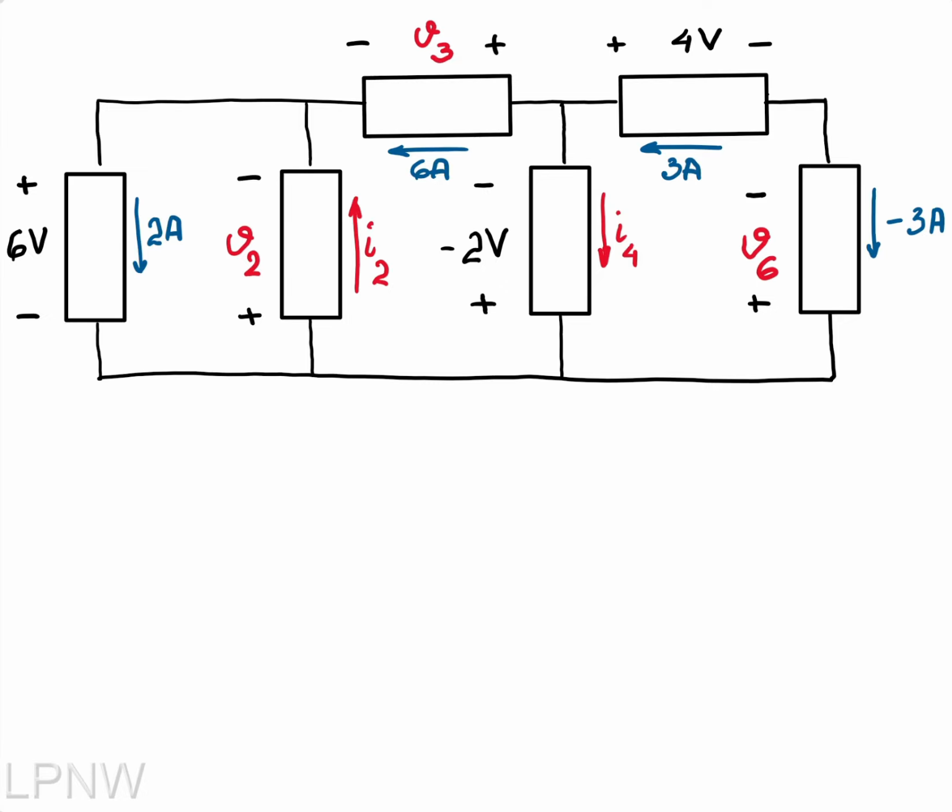It indicates that the algebraic sum of all the voltages inside the loop equals 0, and one very important point in here: never ever change the direction of the loop. Once you choose one particular direction for one of the loops, exactly the same direction has to be applied for every other loop. So in our question, we will have to find currents I2 and I4.